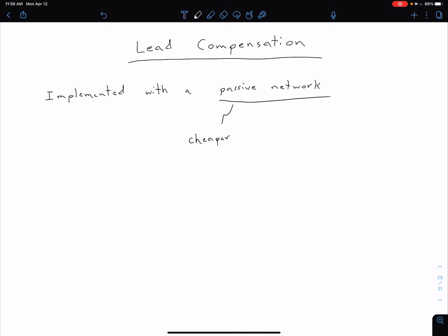However, as we're going to see, we also are going to have to introduce a pole along with our desired zero. So we're going to need a new pole along with our desired zero. However, one thing to keep in mind that we've mentioned previously is that this lead compensation does reduce the noise from differentiation compared to an ideal PD controller. So it reduces noise from our differentiation.